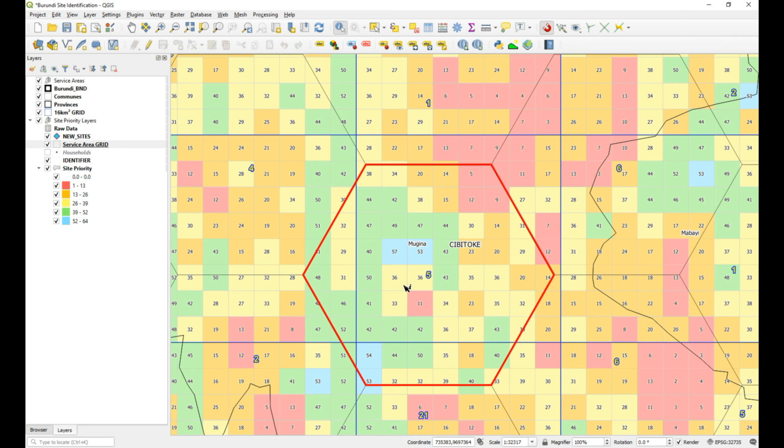Alright, so if we need 5 well points inside this cell, there's a couple of things to bear in mind. I guess spreading them out would help with regards to access to the various households. But let's start off by just identifying the most obvious one, which is this block here, 57.